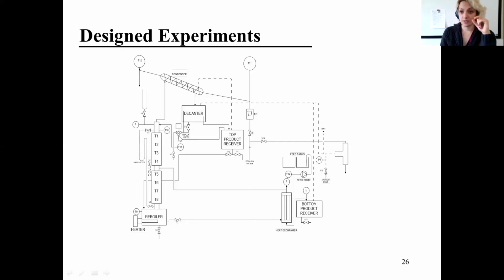And we call it the reflux ratio. Let's say I want to generate methanol. The methanol should have some purity, right? To reach that specific purity, I would return some of the products to the column to use the heat that I have in the column again. And then I have the bottom products.